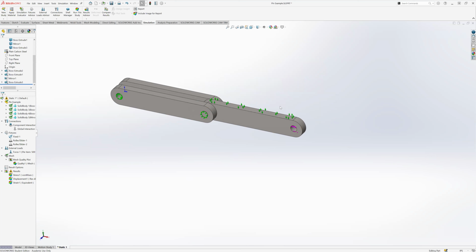So now in this case, this is not going to be able to rotate around. It's only going to be able to slide along this face here. So this face cannot go up and down. Think of this almost like a wall. This component can't penetrate that invisible wall. Sometimes there's another type of constraint you'll hear people talk about, called the virtual wall, which is very similar to this. So we'll do this and then I'll do a mesh and run one more time.